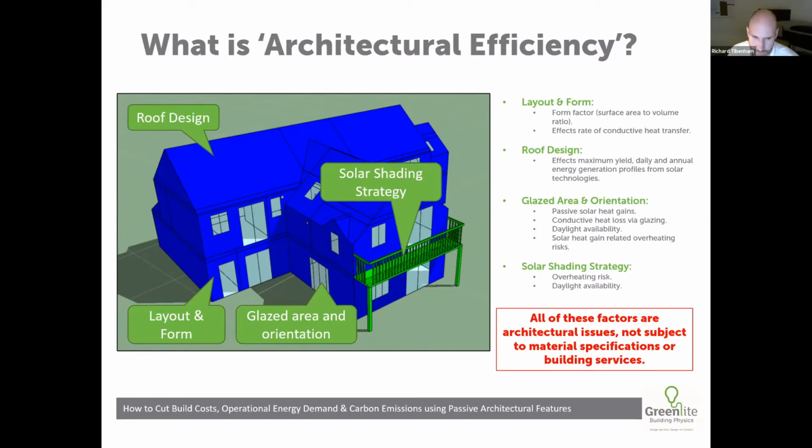the building. Now in this case, we're looking at the heating load and how that can be improved in terms of a dwelling. But the same principles can equally be applied to an office, perhaps. And in an office, you'd probably be looking to optimize daylight availability, because artificial lighting is normally one of the higher fixed building service energy loads in that context.